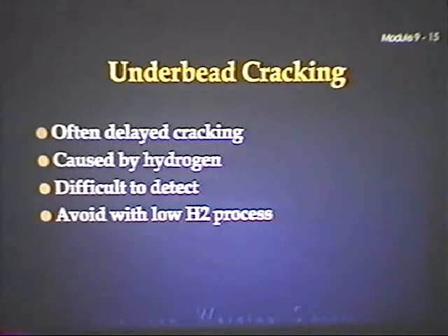Underbead cracking, it's often delayed. You can finish a weld, walk away from it, and think, boy, that's pretty, and come back the next day, and it'll be cracked. That's particularly true in certain types of steel. It's caused by hydrogen. It's difficult to detect, and you can avoid it using the low hydrogen process.